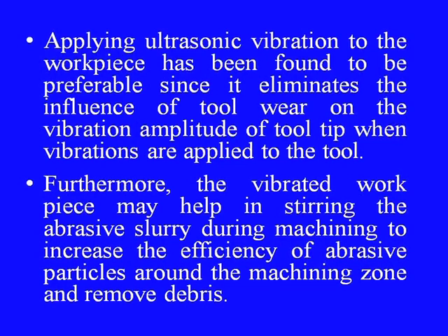Applying ultrasonic vibration to the workpiece has been found to be preferable, since it eliminates the influence of tool wear on the vibration amplitude of the tool tip when vibrations are applied to the tool. This was basically the motivation while developing the version where the ultrasonic frequency will be given to the workpiece itself instead of the tool.